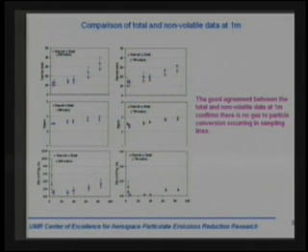The other situation that we need to address, particularly at 1 meter, we are going to argue that at that point where we're sampling very close to the exit plane, none of the volatile aerosol has formed yet, that will subsequently form as the plume expands. And there should be no volatile material forming in the sample line. And so what we can measure is the total aerosol, and then we can take a thermal denuder on the input line and totally evaporate all of the condensed material, if there should be any, and look at the size distribution of that non-volatile component that would be left.